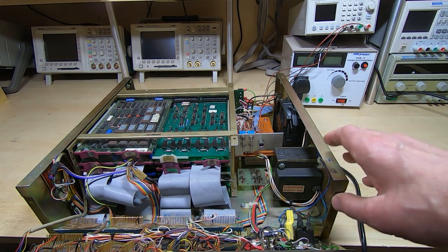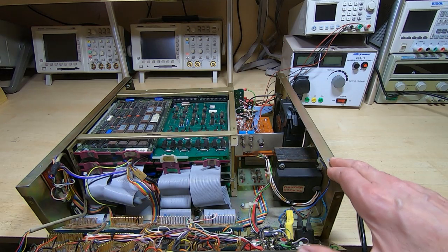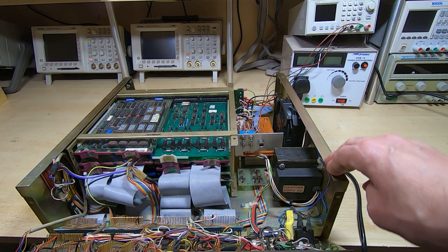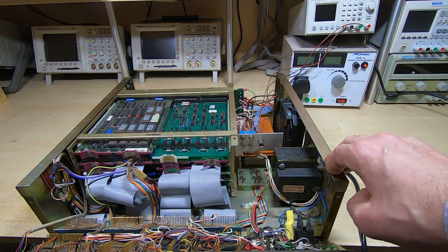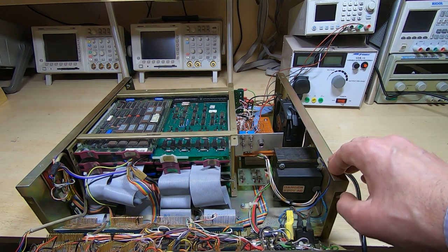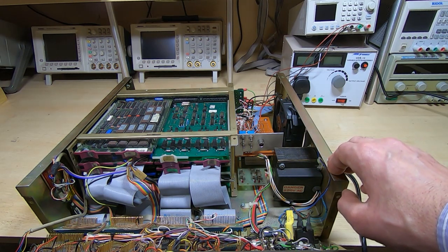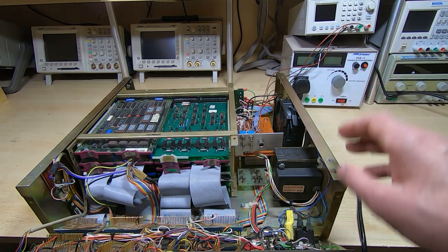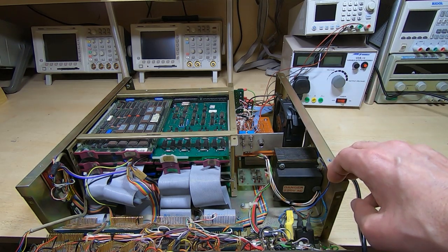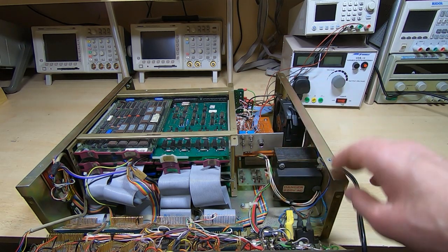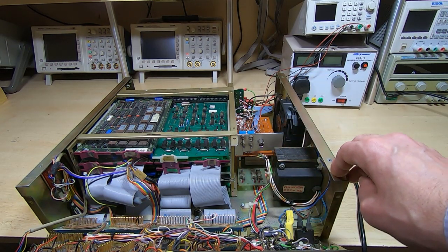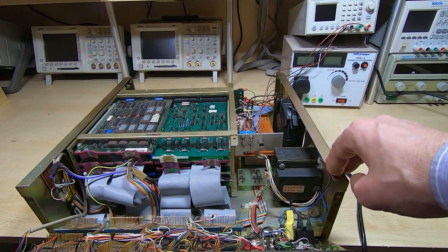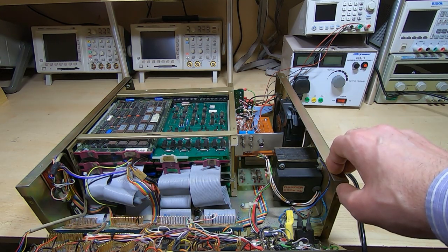So that said, in the first video I introduced this, I showed it booting up, but the problem is that it's not going through the proper sequence once the main program starts. It's part of a CNC system, so when the main program is started, we should be seeing the values for the X, Y and Z encoders shown on the terminal, and we weren't seeing anything. We were seeing the startup code and nothing else. The system didn't seem to crash. It wasn't hitting the reset vector, so something strange is going on.